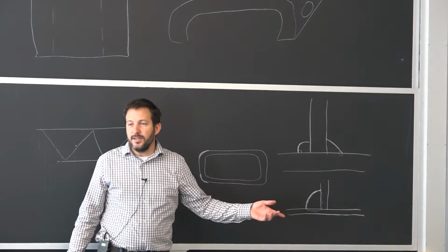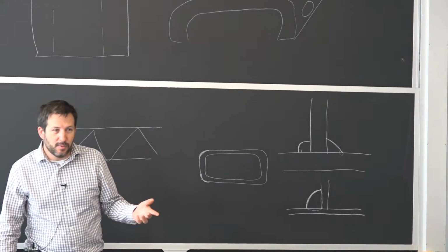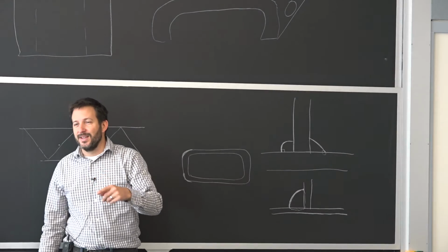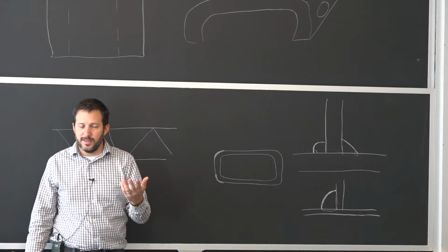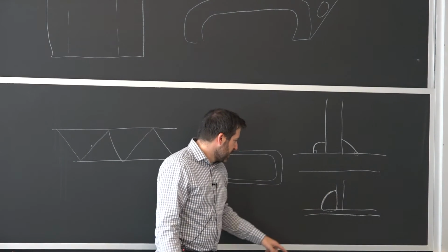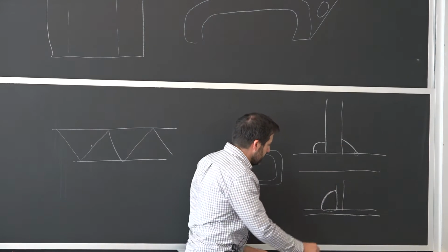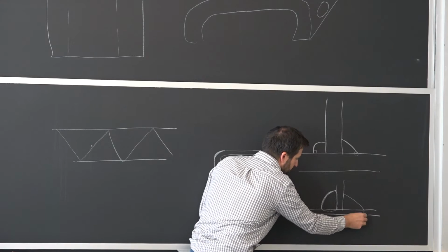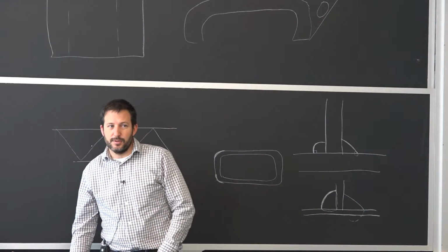And it could be that they don't have fusion everywhere, but it's so big of a weld, as opposed to the thickness of the membrane going all around the equipment, that you don't have to worry about it typically. It's done this way, and the reason is by limiting that fusion, you don't have a burn through. So if you try to do this weld here, let's do it to the other side, it will burn through, and then things don't go well when you start doing that.